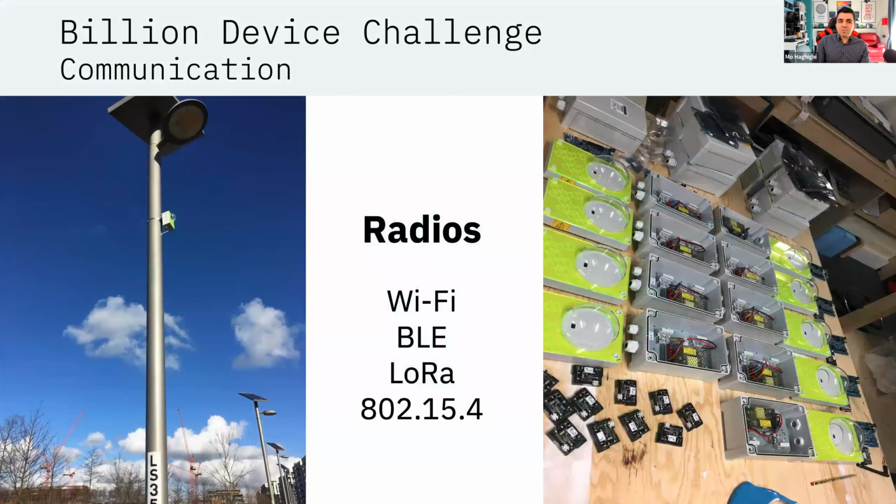So what we had to do was, Wi-Fi was already included in our Intel Edison devices. We had BLE, but then we had to include a LoRa device and 802.15.4, Zigbee, for instance, in order to create a mesh network as well. So LoRa was for long distance communication. And at the same time, we had 802.15.4 for creating a mesh network across the park. And those devices that you see in this photo were small boxes, waterproof, weatherproof, and we had to install these devices across the park.